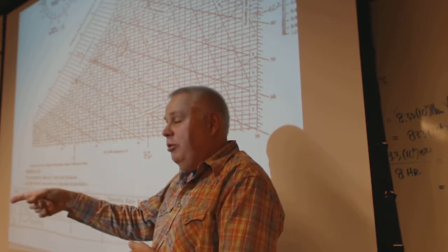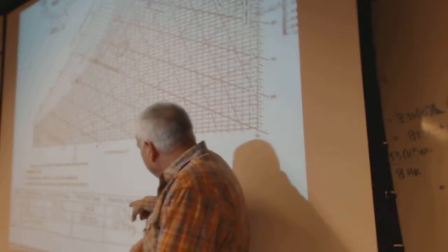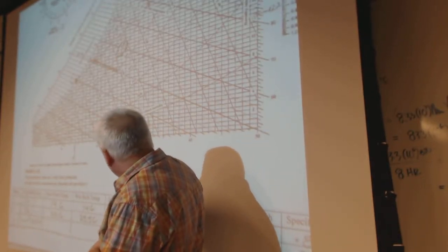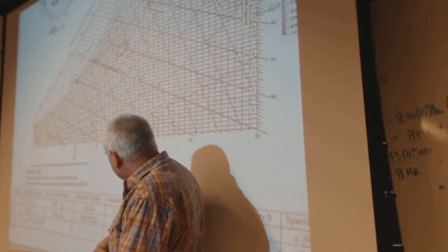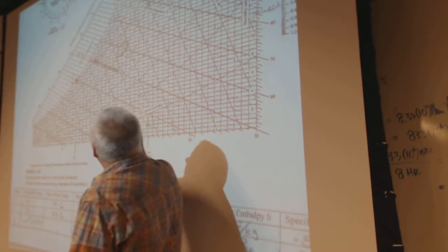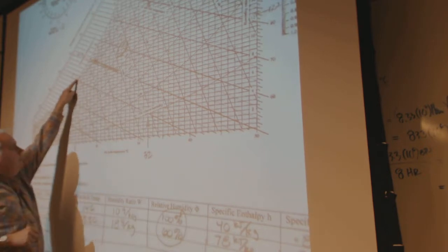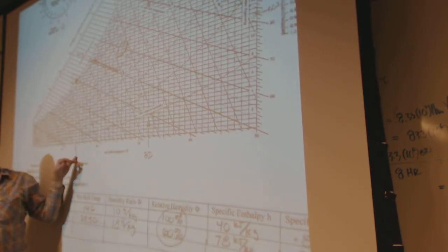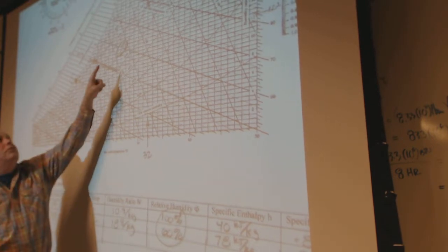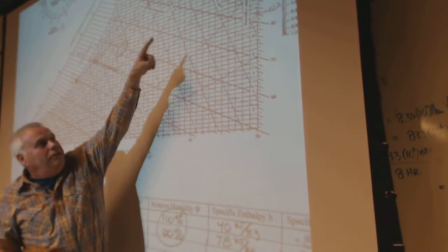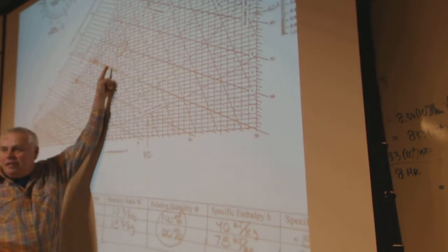There would be one problem like this. By the way, take the humidity ratio here: if I took some air with this much moisture in it, and that air was at 32 and I chilled it down to 14 degrees, what would my path look like? Nothing's going to change on the horizontal scale. The moisture stays the same until I hit saturation, and then it comes down.